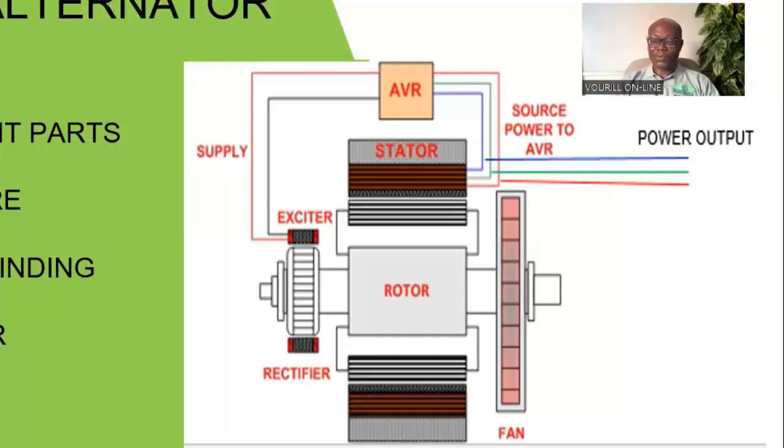There are some where the exciter field is stationary, fed from the exciter transformer, which converts whatever is fed into it into regulated DC voltage that is sent to the field by slip rings.